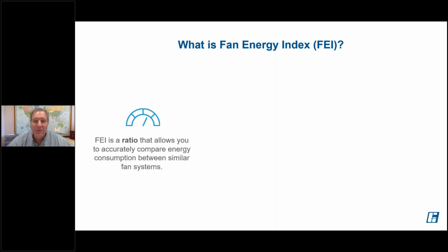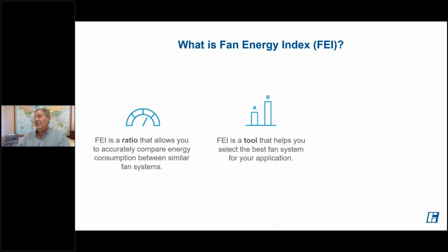And you're going to hear this multiple times, but in the case of FEI, bigger is better. So a fan with an FEI of 2 compared to an FEI of 1 will use about half the power of the fan with an FEI of 1. Again, just a simple ratio that allows you to easily compare the power consumption of 2 different fans.